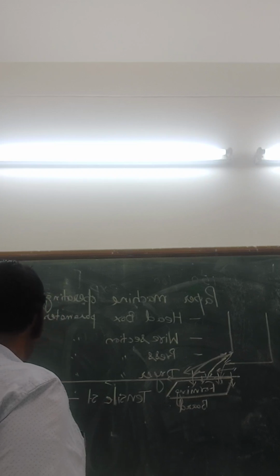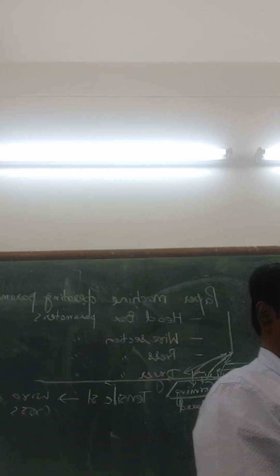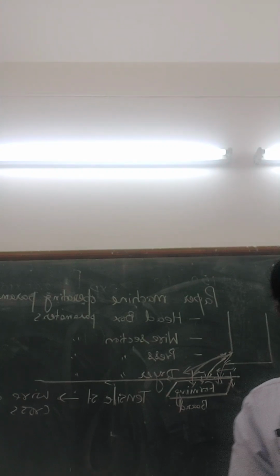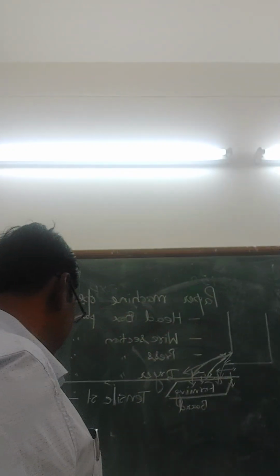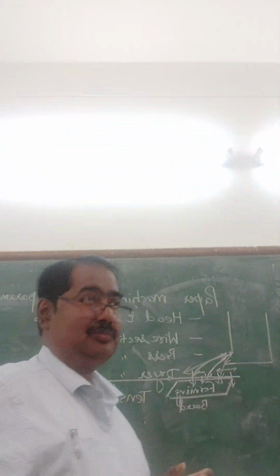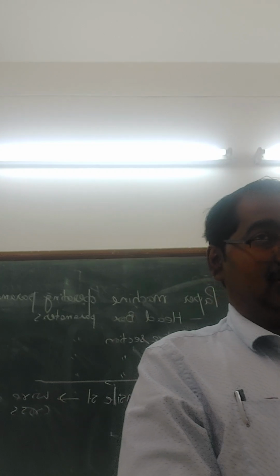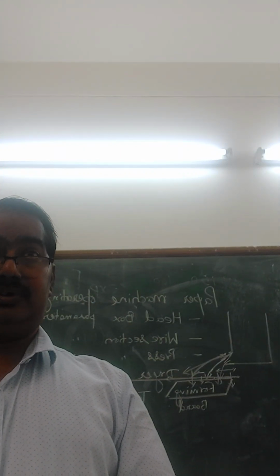So whenever we are measuring the strength of the paper, we are measuring in two directions. Like if you are taking the page from a notebook, you will find it has two directions, one is lengthwise and the other widthwise. If you measure the tensile strength by taking samples, both directions will have different strength, and there will be a significant difference. That means the difference will be nearby, take for example, 20%, 30% like that. Are you getting the point?